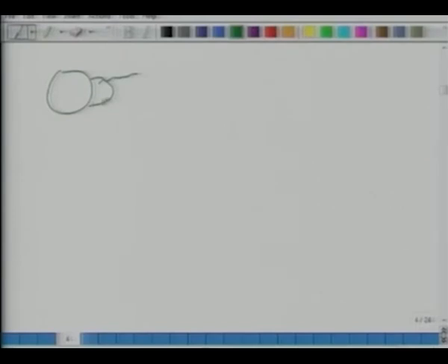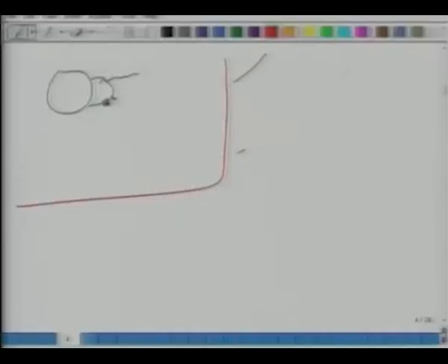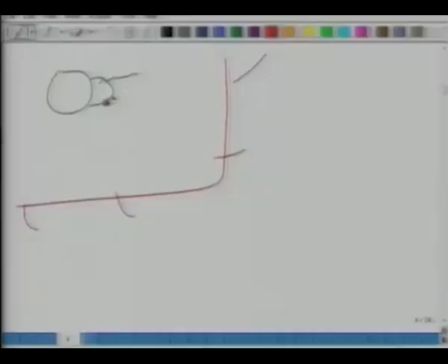So if you place a transducer here, and also if a microphone can be placed here, then it does not matter from which point the noise is coming. The noise is being sensed fairly close to the ear, and the corrective sound is also being generated fairly close to the ear. So because of this, this kind of an approach can handle sources of noise which are distributed in nature.